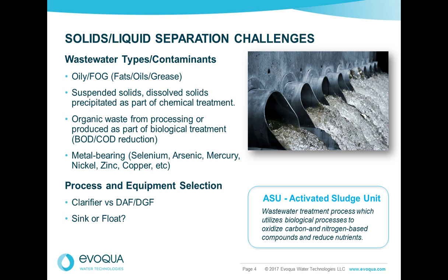I mean, all of these systems are fundamentally the same, that being the separation of solids from the water, but they require unique considerations when designing and operating the wastewater system. One of the concepts to think about during today's sessions is the basis for selecting the right separation equipment, whether that's a clarifier or a DAF, whether we're going to sink the solids or float them.